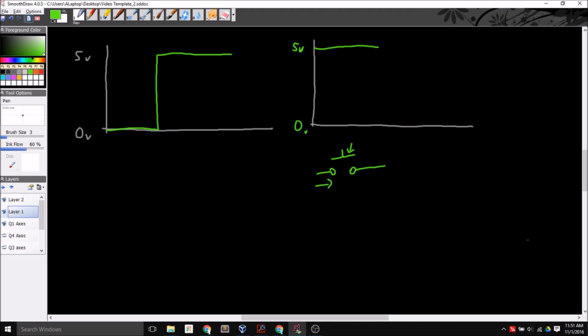Now, on an Arduino, usually what we have done is we have one end that's connected to your Arduino pin, and the other side might go to my ground, which is my 0 volts. Then I have what's called a pull-up resistor, which I drew on the bottom, and it is connected to 5 volts. In fact, this pull-up resistor is built into the Arduino, and we can talk about that later as well. If I'm doing a button in this fashion, then all the time that the button is not pushed, I'm getting a digital HIGH on that input. And when I push the button, it connects this ground to the Arduino input, and that gives me a digital LOW.